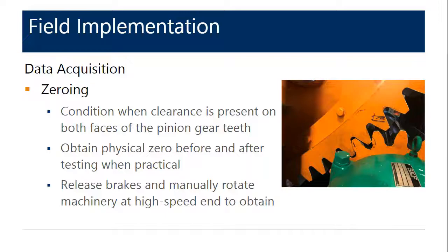substantial stored energy that is released when the drive machinery brakes are released. This could be dangerous to the person releasing the brakes, and it could result in a little bit of movement of the leaf that may cause a problem. This is specifically applicable for rail bridges. Only qualified personnel should perform this type of work.